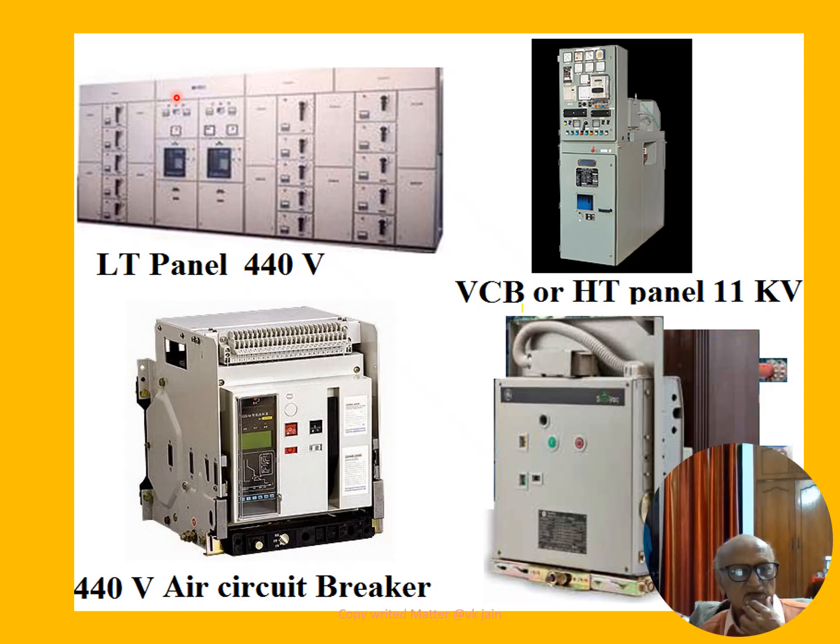The busbars are provided here, and from this busbar connection is taken through these switches. There may be several switches connected to the busbar. Busbar is running here three phase, so there will be four busbars and one earth busbar also,